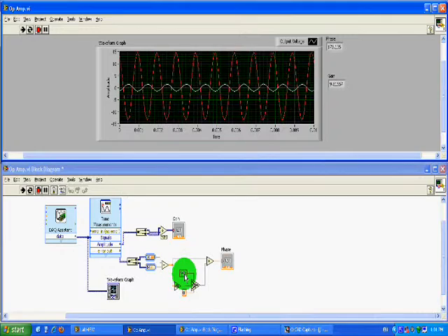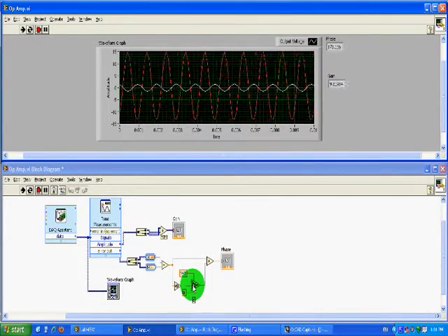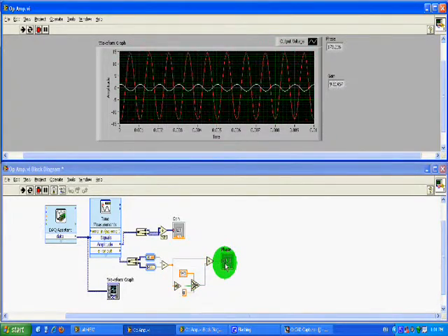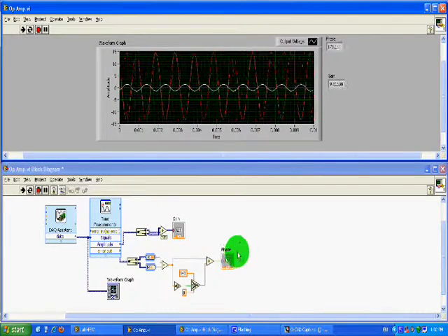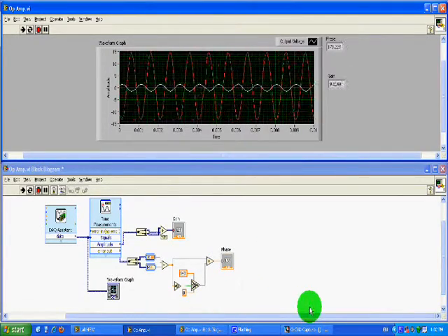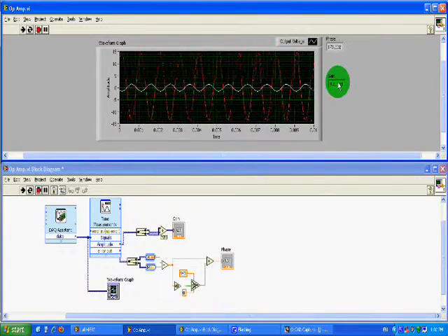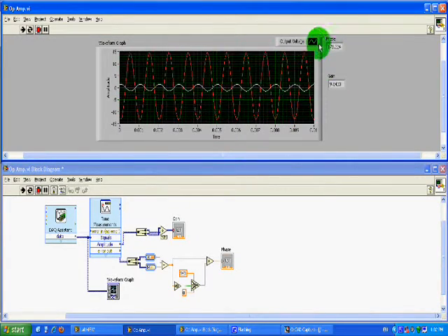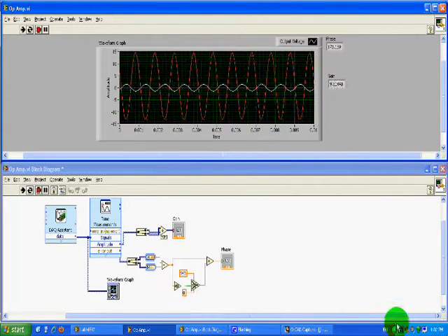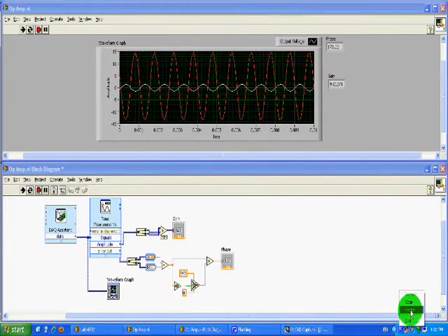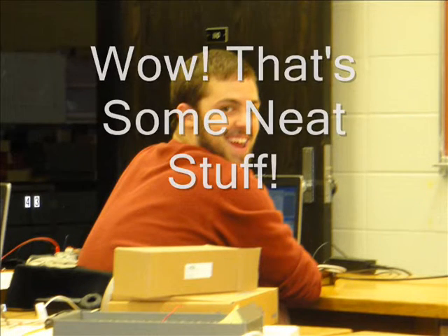Because we get negative 180 and 180 approximately, and we don't want a negative, we add 360 to it. So if it's less than 0, we add 360, and that will give us our phase, which stays right around 180 because that's the phase shift. Then our gain is approximately 10 because our resistors are 10K and 100K, so the ratio is approximately 10.